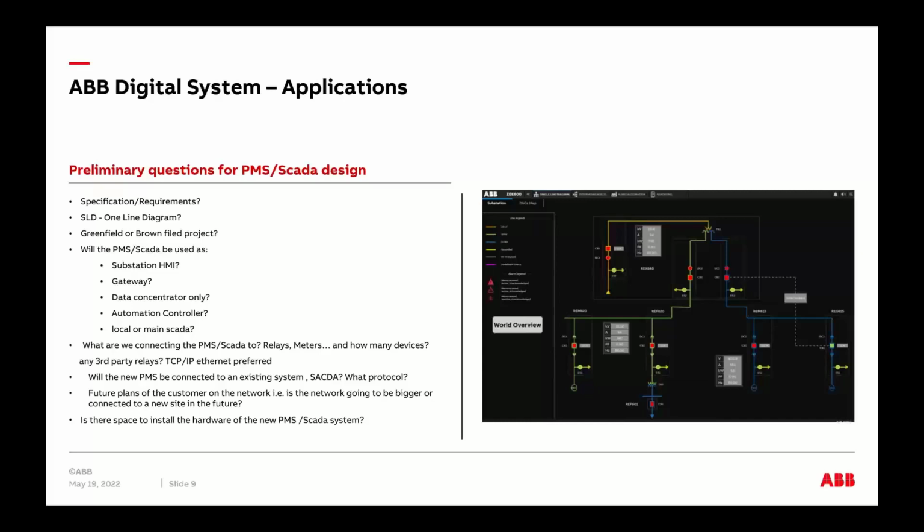So you give them the right tags. I'm using the word tags and the word signal at the same time. For example, if you pull a system that has 10 devices, and you are using, let's say, 1500 tags. Remember, one tag is equal to one signal. So you take those 1500 divided by 10, and you will see I will have about, let's say, 150 signals for each device.